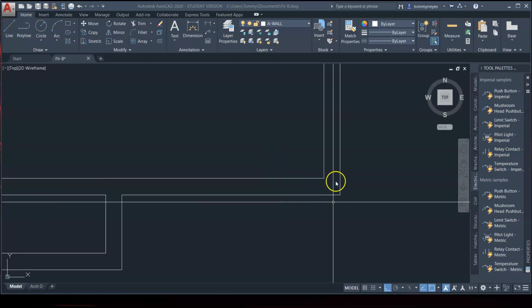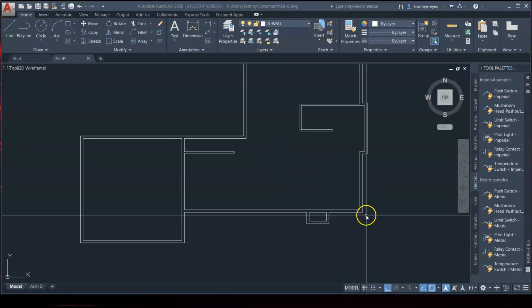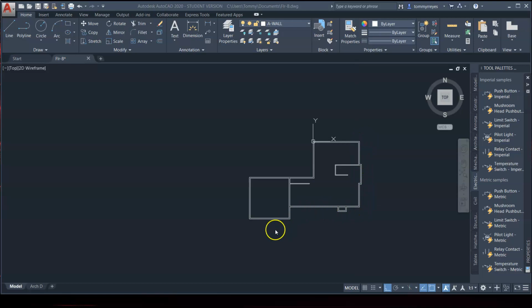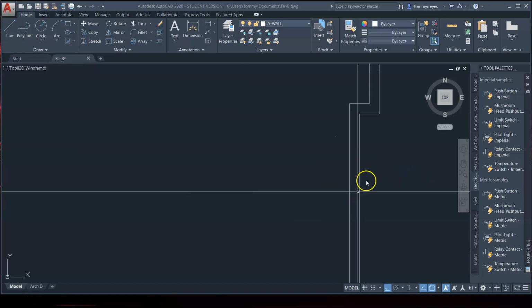The thicker walls in the basement are because they're like retaining walls. It's underground. We don't want the soil material buckling these walls. They need to be strong and sturdy to hold back the dirt and soil around this basement. They dig a hole in the ground, put up all these really sturdy walls using reinforcement and concrete and what have you. That's why they're so thick.